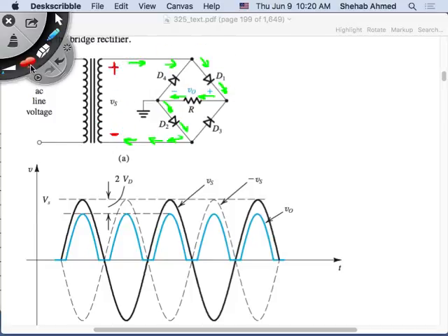How about when D3 is open? D3 and D4 will be open. So what is the voltage across D3? It's the V output. No. This is current flowing here, so this is the voltage drop. And this is current flowing through here, so the diode voltage drop is this way. So the rating for this diode is what? Is V output, which is equal to Vs, right?